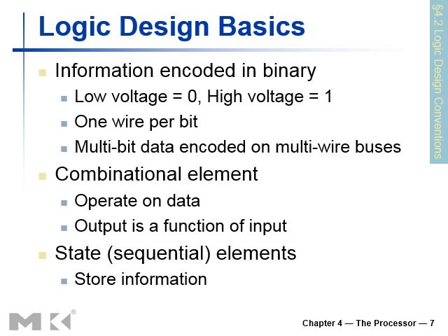So the first important thing is that the information which we need to process in a single cycle processor is in binary. That is basically the machine code, and depending upon the implementation technology, the low voltage represents the zero state or the logic zero, and the high voltage represents the one state. So what that means in terms of voltages is dependent upon the implementation technology. For example, if you're using the TTL technology, that is the transistor-transistor logic technology, in order to implement our design, then the definition of 0 and 1 is defined as per that standard. But if you are using some other standard, for example the CMOS standard, then definitely the definition of 0 and 1 is represented according to that standard. So basically 0 belongs to the lowest range in that range distribution, and 1 belongs to the upper or highest range.